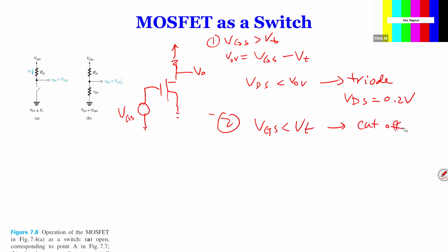That 0.2 volts is only true for small signal amplifiers. If you go to actual switch devices, that voltage is actually much more than 0.2. Sometimes it can go to 1 volt, 2 volts, 3 volts. It depends on the voltage level. If the switch has like 1,200 volts, for example, the voltage drop can get up to more than 2 to 3 volts. And it's usually constant.